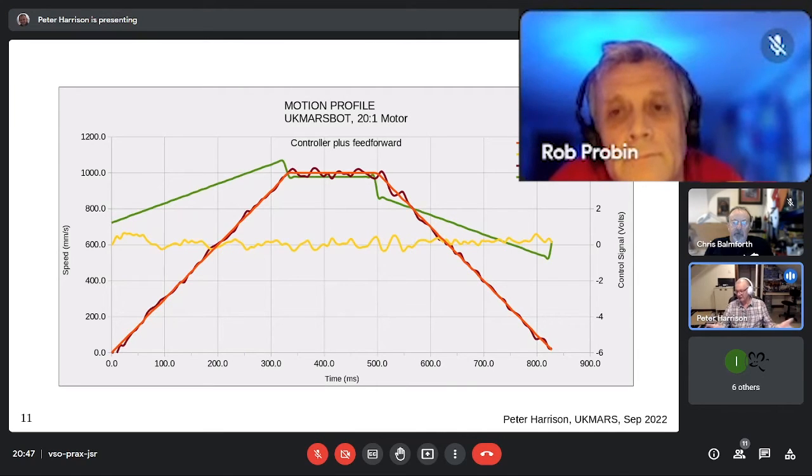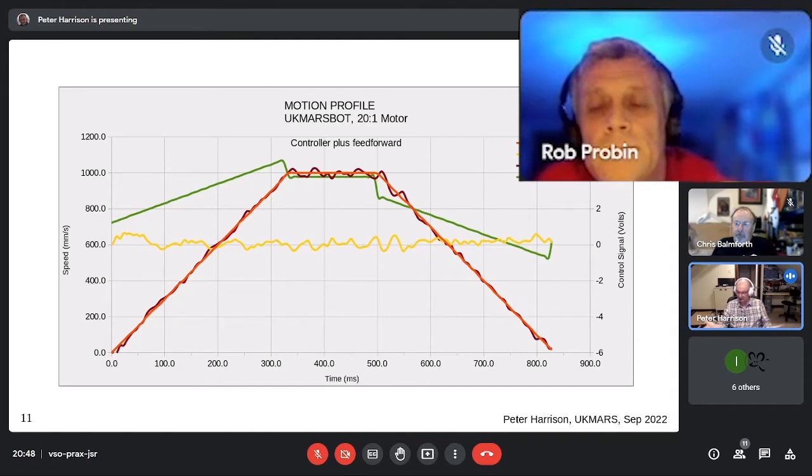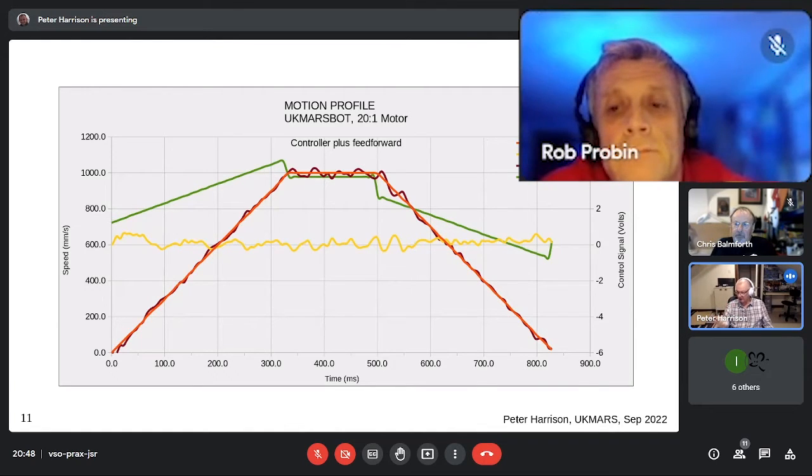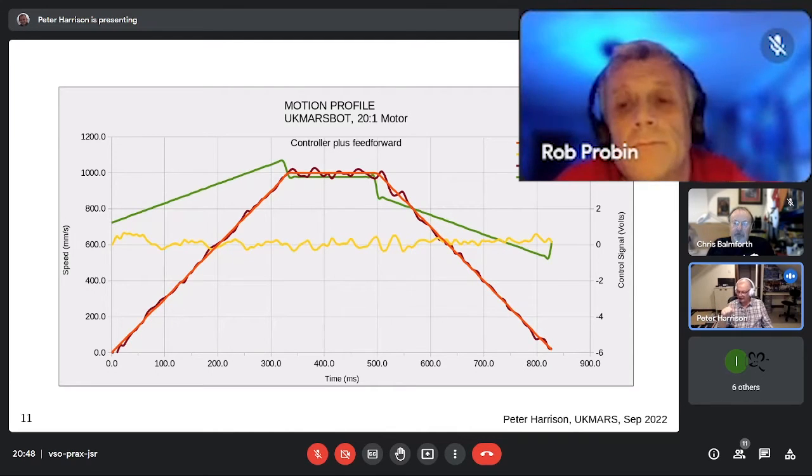If I was going to video the tests, but a fit of laziness overcame me, and I videoed the feed forward only, the feedback only, and the feedback plus feed forward, and showed you the 3 of them and asked you to say which one you thought was which, you'd get it wrong. You can't tell the difference, because people are pretty poor at that. But when it comes to running at top speed around a maze and missing a post by 2 millimeters, at several meters per second, trust me, this is a difference you want to have.